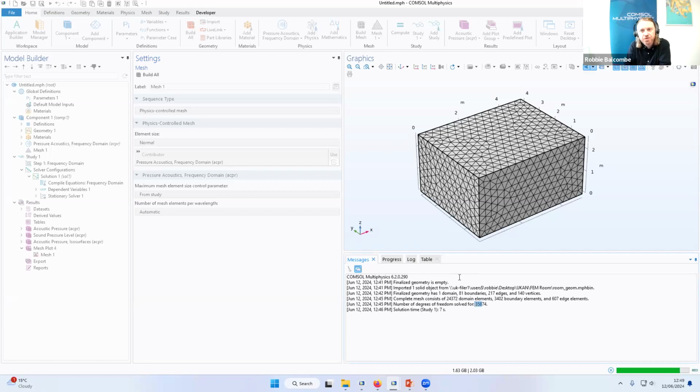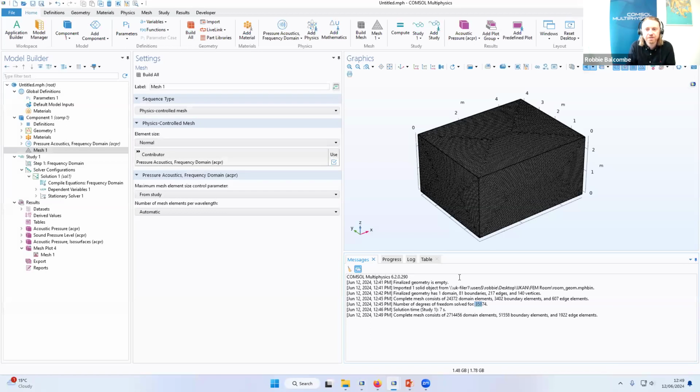Now, if you have the resources available to you, you could conceivably compute this model using, say, HPC computing or something like that, but it would be a heavy simulation to run. So this is where we can consider switching from using a wave-based solution that's either finite element or boundary element based to using a ray approach instead, because it provides us with a more favorable method in terms of the computational cost of computing.